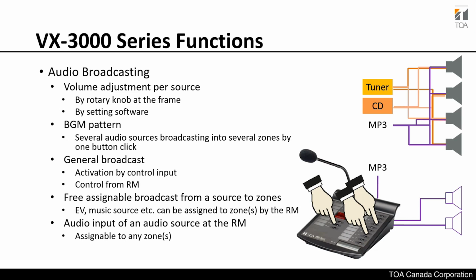So you can program it to your heart's content and take any audio input and then send it out to the zone. In the case of triggers, we've discussed the microphone trigger, triggering by a contact input to the VX3000, and triggering via an automatic time setting.